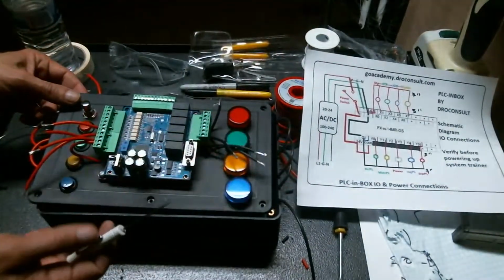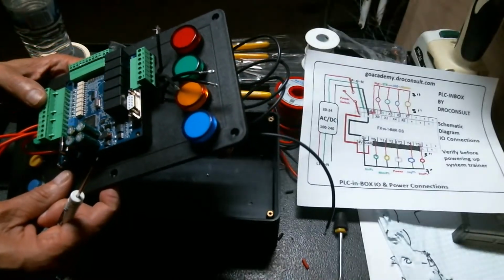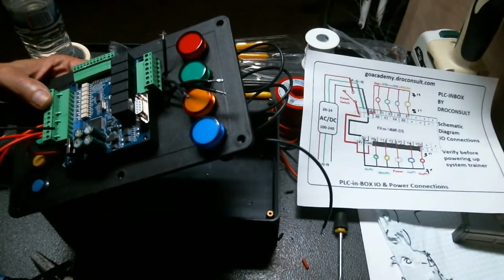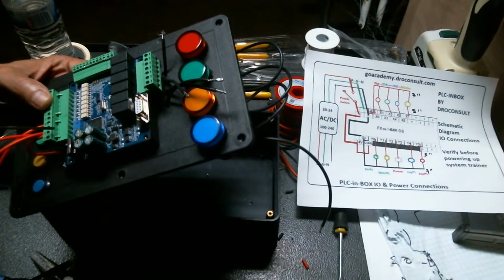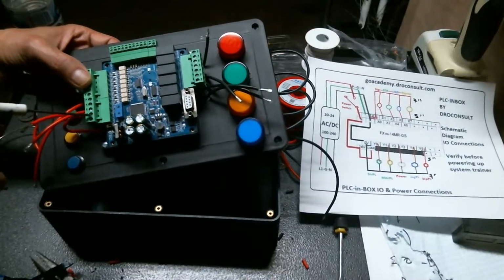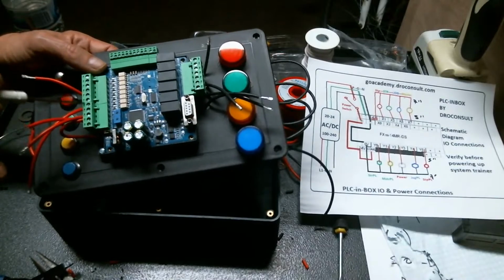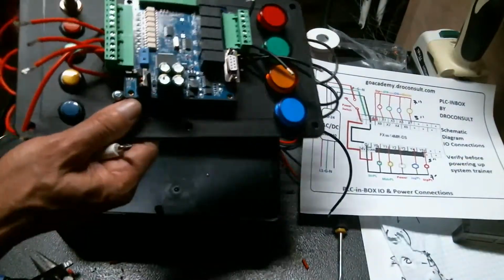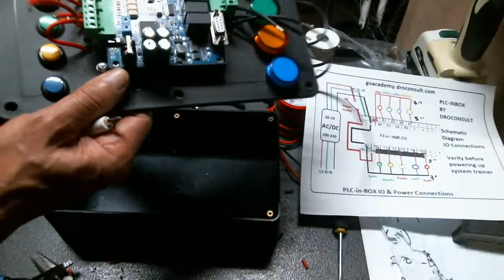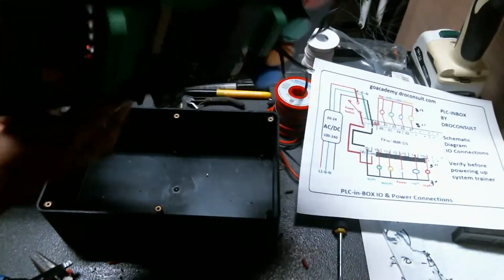So if I follow the schematic, all right, I'm going to look for X1. And so F1 is, let's see, terminal 5. So terminal 5, my controller here is 1, 2, 3, 4, 5. That's going to be X1 right there. Okay. So I'm going to remove this wire just to redo this. Okay. And the red wire,